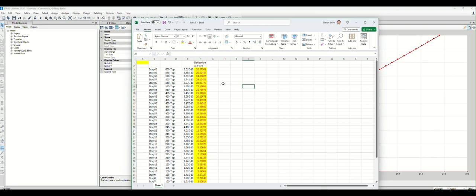We maybe want to stop or limit our wall thickness at some 24, 26 inches, because you don't want to keep increasing the wall thickness, because we're losing some leasable space, or continuously increasing thickness may not be efficient because your moment arm is almost identical, but you're increasing the flange thickness. So we better think about other more efficient ways to increase the stiffness, which we're going to consider some outriggers later on. So this is the first step.